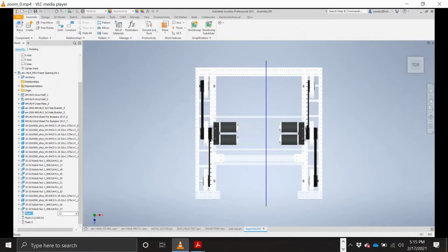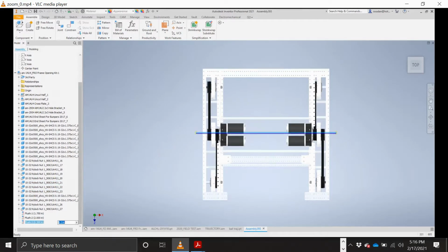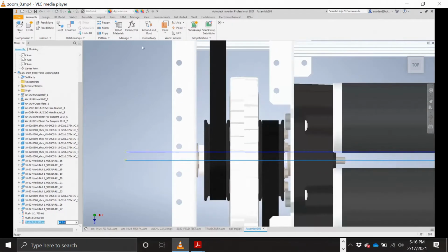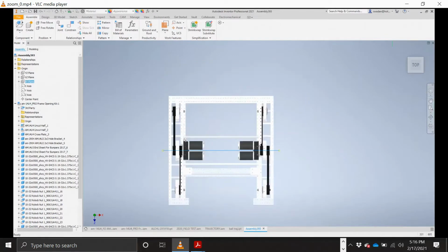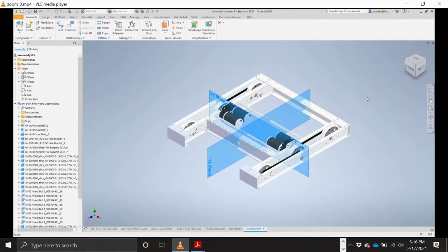What I did is I just mated my X plane to my X plane, my Y plane to my Y plane. So I need to create an offset, looks like maybe 2 inches on one dimension and 0.3 inches on the other, and that gets me my nice mirrored XY planes. And this chassis is the drop-centered wheel chassis, correct? Yes, it's got 6 wheels and 4 motors, and this should be a very versatile chassis that should match up against most other robots.